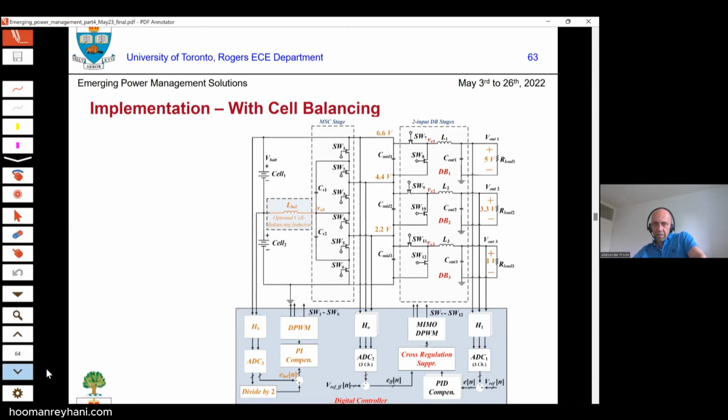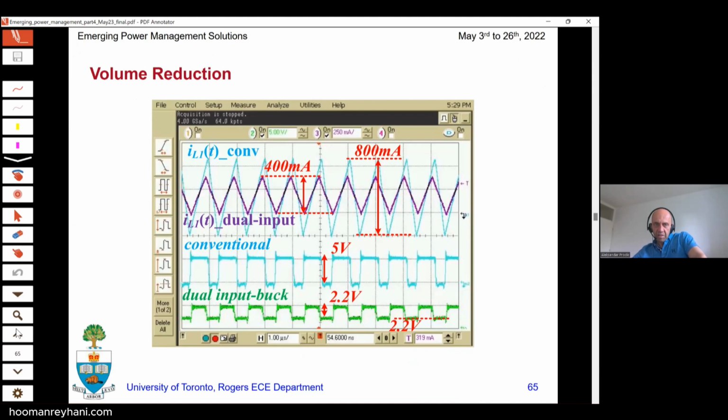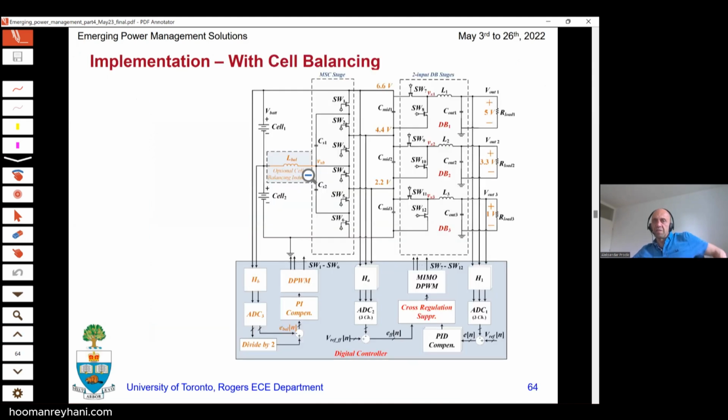And what is really interesting here is that if you put an inductor, you also improve the efficiency of the switch cap stage, because now you always have charging and discharging of the caps through the inductor, meaning that you're avoiding a typical problem for switch cap circuits, and I'm going to address it soon, related to non-adiabatic charging, and improving efficiency of the front end stage.